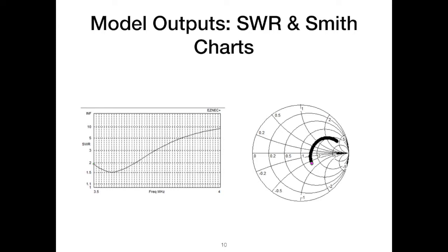We also added additional length later in the day as we started trying to use the antenna. We put an antenna analyzer on it and looked at it and said, in the real world, because remember this is a model, right? Your mileage may differ a little bit when you get into the physical world. So we put an antenna analyzer on it and said, this doesn't look real great, so let's add some length to this.